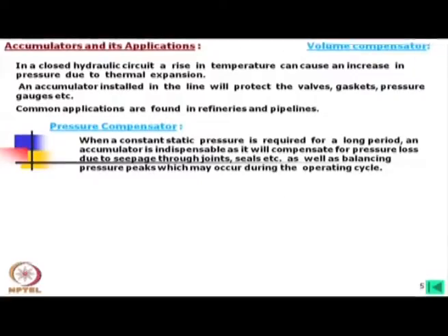Now, we will think of the pressure compensator. When a constant static pressure is required for a long period, an accumulator is indispensable, as it will compensate for pressure loss due to seepage through joints, seals, etc., as well as balance pressure peaks which may occur during the operating cycle. So, this means that